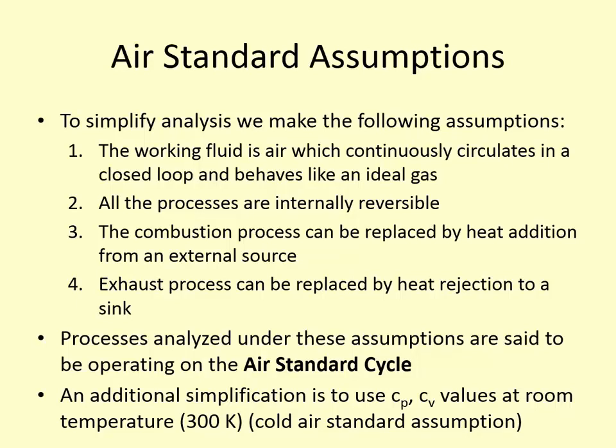And one additional assumption, or simplification, that we can make is that we're going to use the C sub P and C sub V values at room temperature, which makes it the cold air standard assumption. So rather than needing to know the temperature of the exhaust gases or anything like that, we just say, okay, we're assuming it's air at room temperature. This is the cold air standard assumption, and that's how we're going to analyze this device. And again, it's an idealized version of what's actually happening in the system. But if we're analyzing all of our designs that way, then we can compare them one to another, and the same general trends will apply.